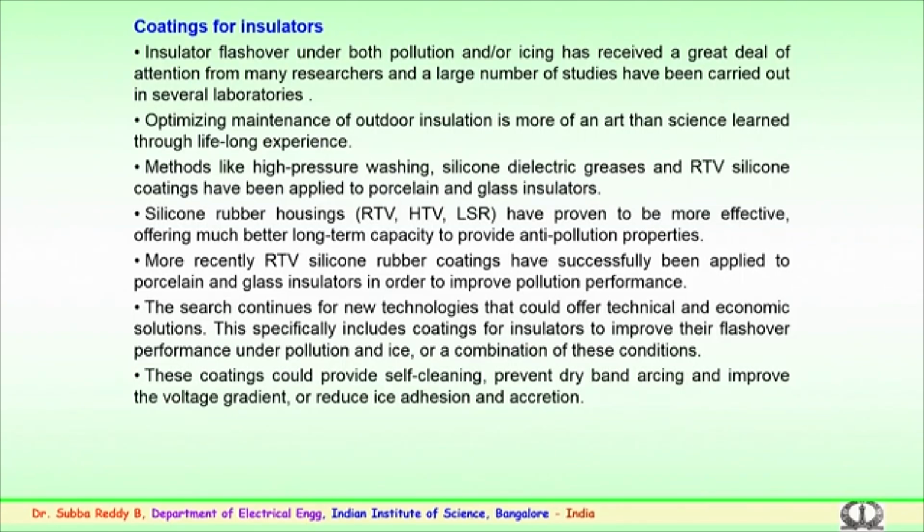Methods like high pressure washing, which we discussed during the cleaning process for insulators and other equipment, application of silicone dielectric greases, removal, and then RTV silicone coatings have all been applied to porcelain and glass insulators, and have been followed for a long period of time.